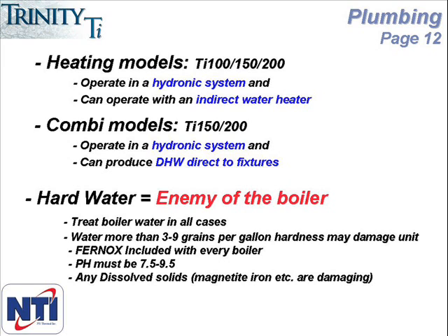In any case, water quality is something that needs to be taken into account. Water hardness levels in excess of 9 grains per gallon hardness can cause damage to the heat exchanger of the unit.